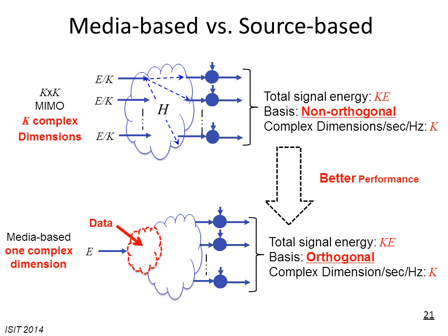Consequently, we have to look at it either as a signal being expanded over a non-orthogonal basis, or as the noise at the receiver being correlated. Although the noise is independent, the two views are equivalent: if you want to look at the signal as independent, the noise will be correlated.